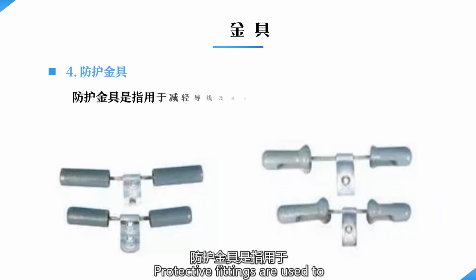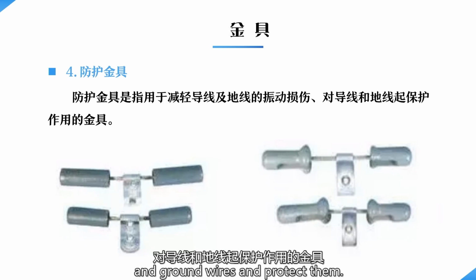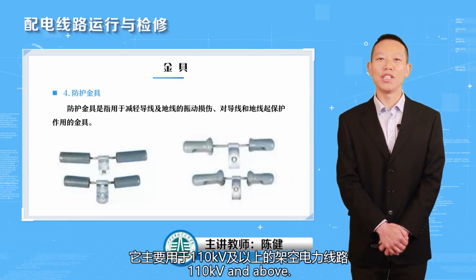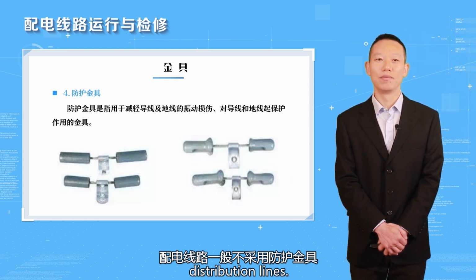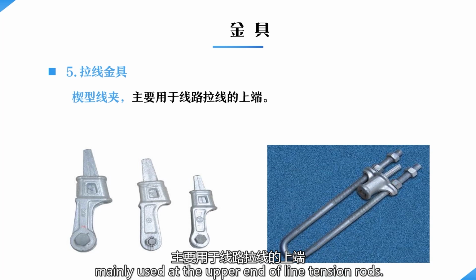Protective fittings are used to reduce the vibration damage of conductors and ground wires and protect them. They are mainly used in overhead power lines with voltages of 110 kV and above. Protective fittings are generally not used in distribution lines. Tension line fittings include wedge line clamps, mainly used at the upper end of line tension rods.